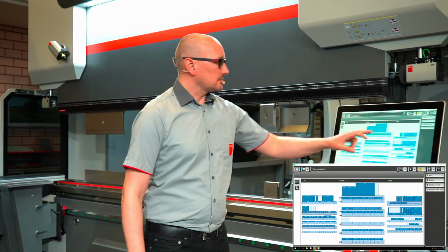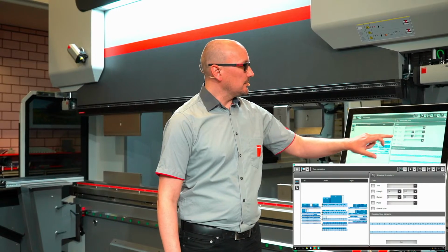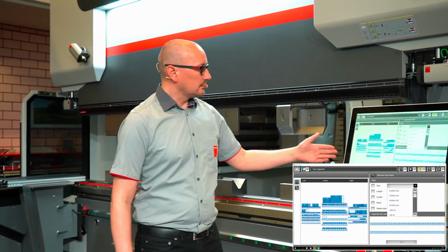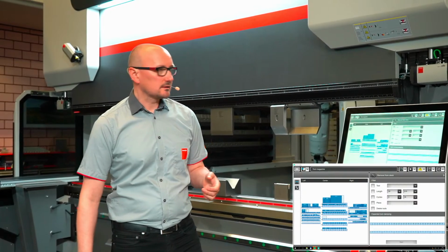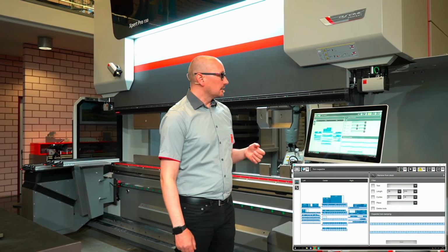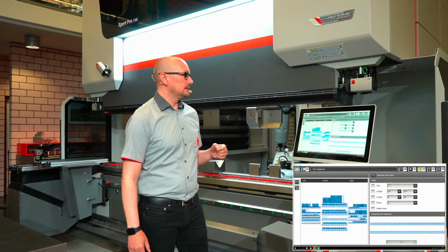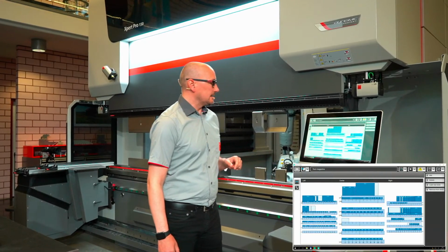And if you have old tools, or tools you will remove because you don't use them very often, you can also say remove from stock. The same way you select your tool, you can also select one area of your tool magazine, however you like. You can also say, I will remove tools with up to 1,000 cycles or 10,000 cycles, so you can control all tools and check this, and when you say, okay, the tools are not good anymore, then you can delete them. You can also say, please delete immediately if you place it out, so the robot knows you will really remove it.